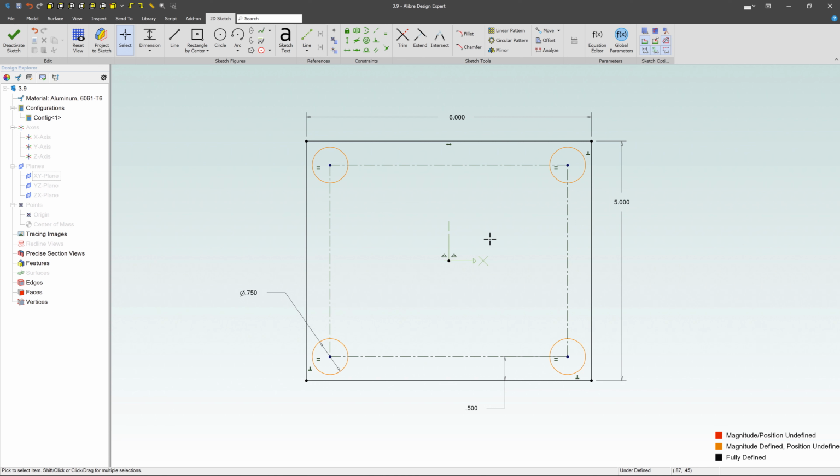And if you're just doing a layout over a building or a piece, and you just know the specific offsets you're going to be doing, it's a great way to just type those values in, offset those lines, and you can get all that data real quickly based upon some starting sketch. Anyways, that's the basics for offsets. Definitely use them. They'll save you a lot of time.